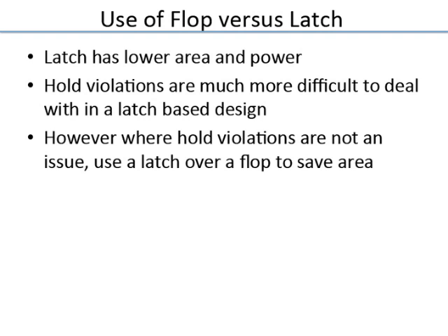But of late, industry is moving to more latch based designs, and some advances have happened in the tools, because with digital design you have to rely on the tools at the end of the day. Small designs you can do by hand, but the designs have millions and millions of gates, so all methodology has to be incorporated in the design tools. Only if the design tools support it can we do this. So now you can start doing latch based design. But remember, when you don't have these problems of hold time and so on, you should definitely think of using a latch or latch type of structure where you optimize and reduce the number of transistors. Okay.